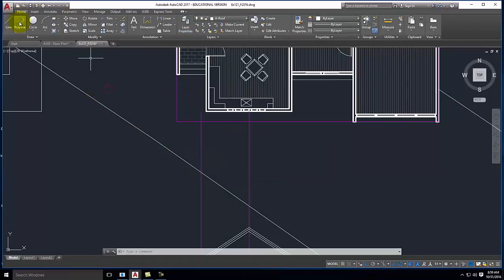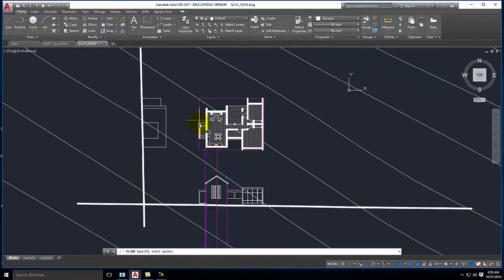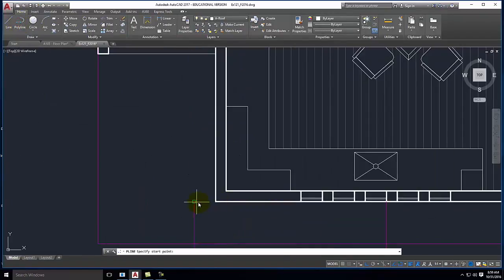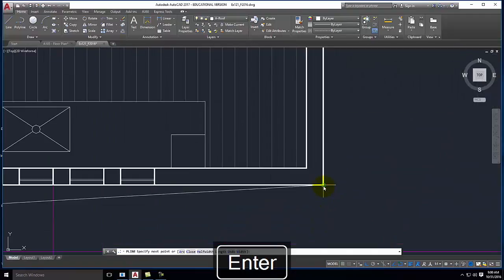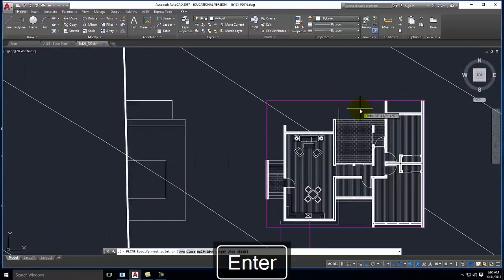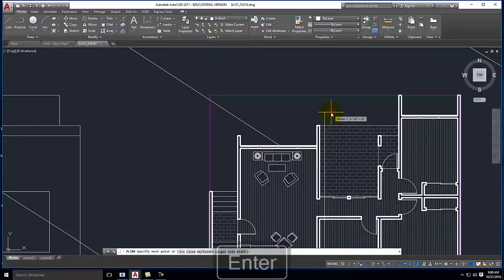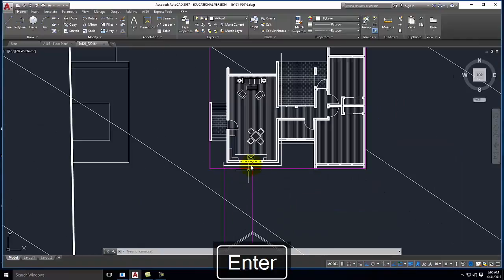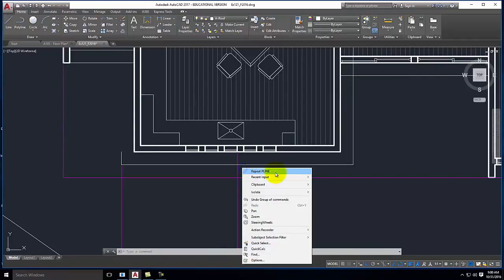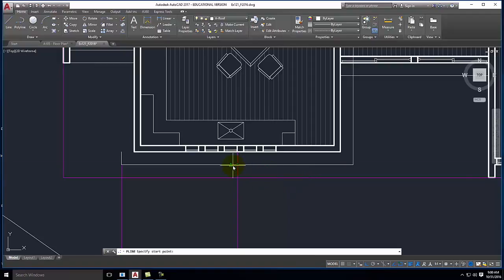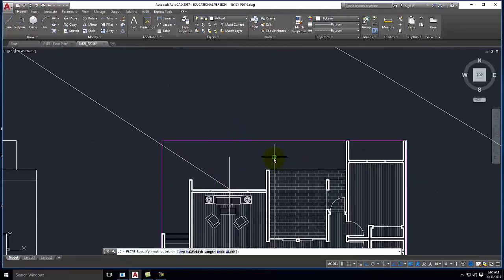And then I can go ahead and come up here with the polyline tool, and I can start to draw what the roof looks like. So we already know that it starts a foot away. So it would be a 1 foot overhang here. We'll go across to right there. It would be over another foot. And then we'd be coming back, etc. Okay, so I'd be working around my building to draw this plan. And then the gable would be right at the center, right there, and it would be going across the building here. I haven't drawn the back side yet, so I don't know what it would look like.